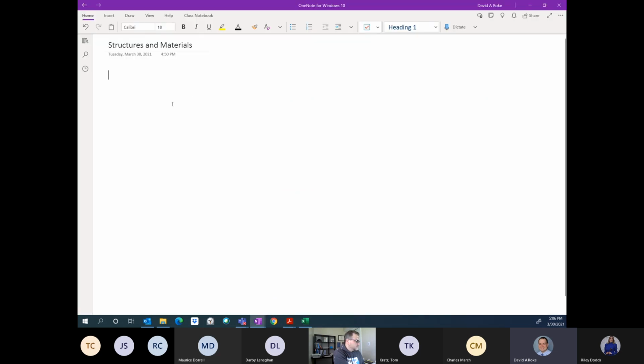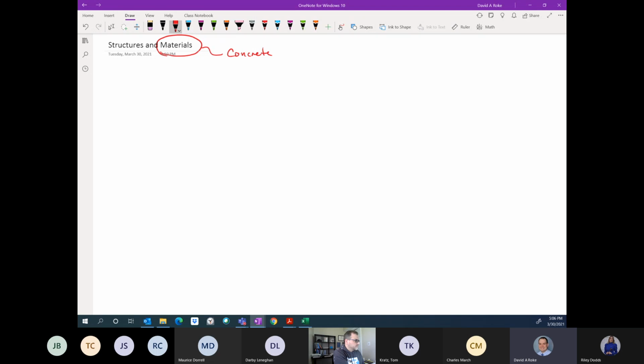I would also like to point out that I've been invited not only to review structures, but also to review materials. And for materials, we're essentially looking at concrete design, concrete mix design for the most part. There are no tables or any information provided about this. So basically, you remember that your water to cement ratio drives your quality and strength. Generally a high water to cement ratio gives you a lower strength, and a low water to cement ratio leads to a higher strength.